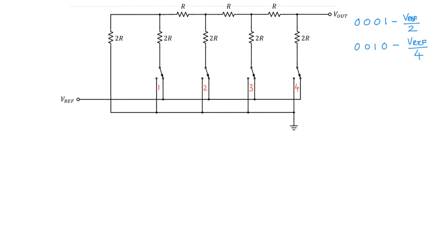Next, we'll look at another code, and we'll use the value 0100. So what we are doing is turning off these switches or connecting them to ground, leaving this one on and turning this off as well. And let's look at what output we get for this circuit.